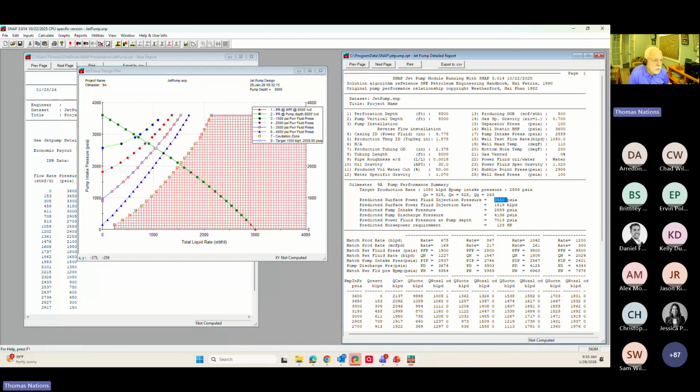Related jet pump design we may have to consider is the erosion rate in the tubing, mainly when we design reverse mode and try to maximize production in a new installation. We usually end up having to reduce the rate to be in range or below standards on erosion rate, so not fully optimizing the well rate. Yeah, certainly you have to be concerned with erosion on your tubulars, as well as your jet pump items. So that has to be taken into consideration with your design and operational methodology.